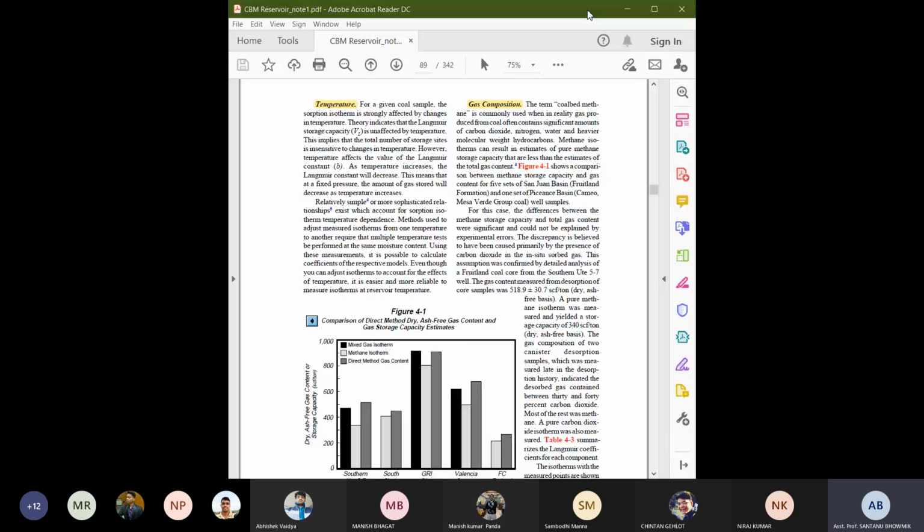So why is it important to know the fraction? If you are not able to know the gas fraction, you will not be able to get it when you reduce the water pressure from the borehole dewatering process. As you take out the water, you will see that the gas is coming, but then you have to separate the gases and know the concentration of the different gases so that you can calculate the partial pressure in the total pressure system, and then with this gas fraction you will be able to calculate the total gas adsorbed in that total pressure system.